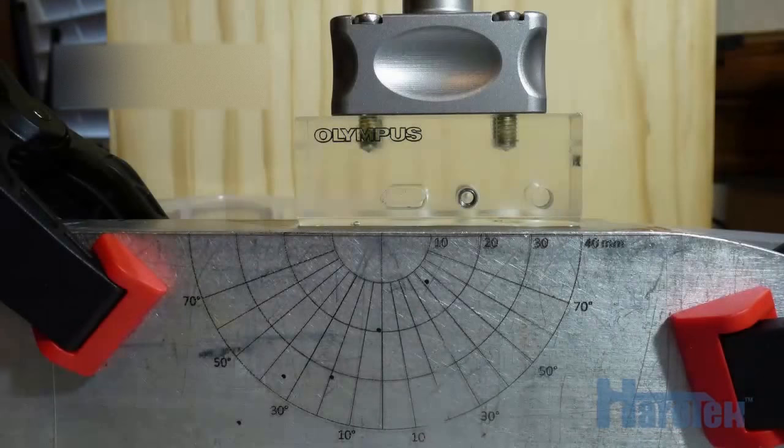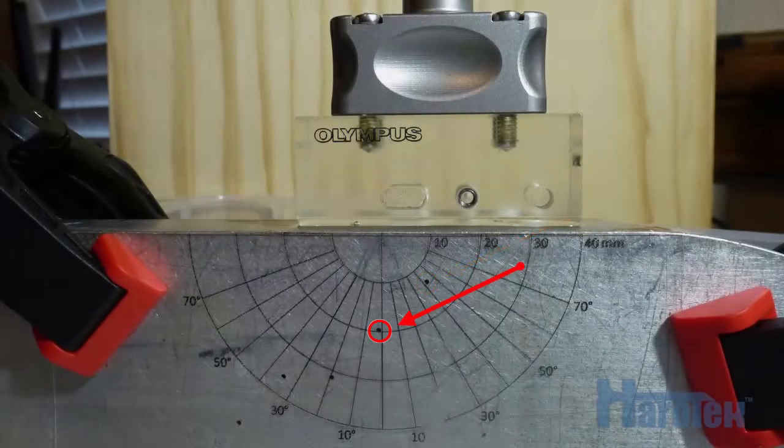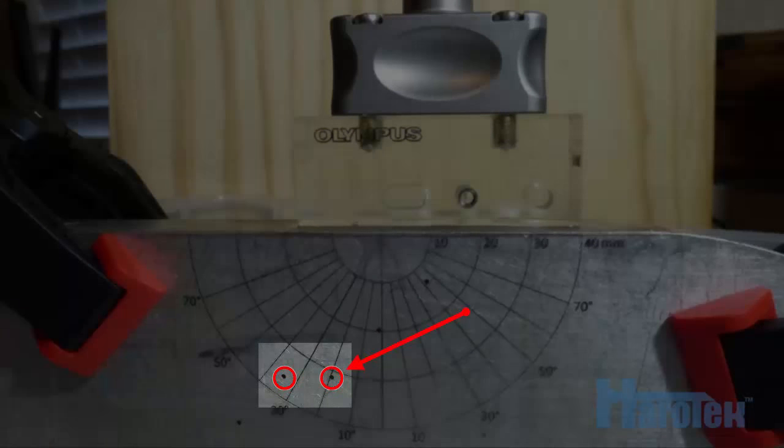The initial experimental setup uses the flat wedge with a 64-element linear probe. The sample is an aluminum block with 1 mm diameter through holes. An overlay indicates the distances and the angles of the holes relative to the approximate entry point of the ultrasonic beam at 0 degree. One hole is at approximately 40 degrees, a little bit more than 10 mm away from the entry point. Another hole is about 20 mm away at nearly 0 degree, and the two other holes are more than 30 mm away at negative 20 and 30 degrees.